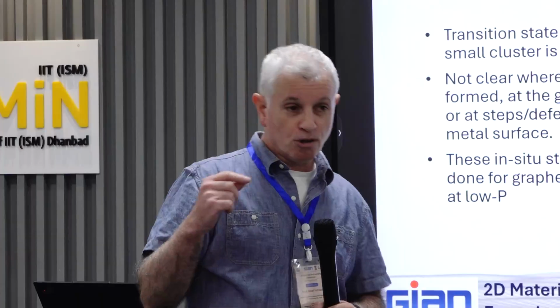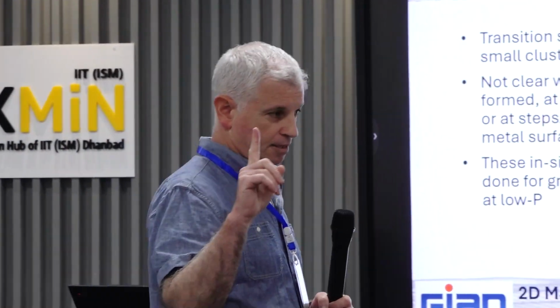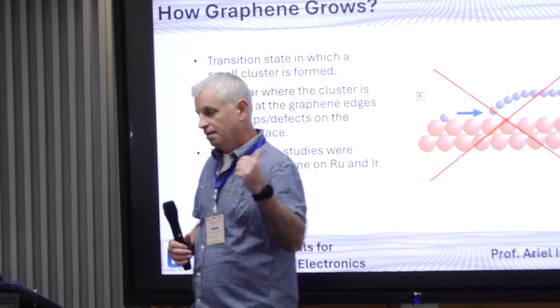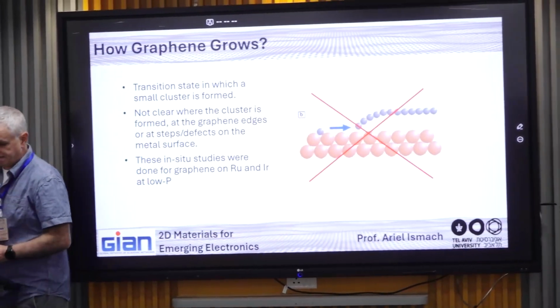That's why the diffusion is so high. The mobility of the atoms on the surface is so high. That's why copper works very well. In contrast to other metals that also have low solubility of carbon, still copper works best. So the solubility is one of the needs. There are many other parameters that influence the growth as well.